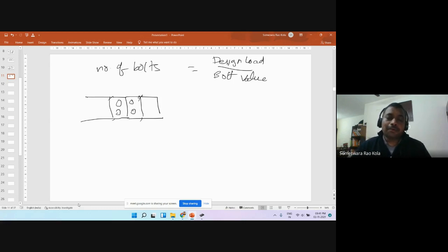Maybe your plates are fine and bolts are fine, but if the cover plates are weak, then it's going to rip off and the connection will fail. So there are some guidelines on choosing these cover plates also. The thickness of the cover plate shall be more than the thickest component in the connection, right?